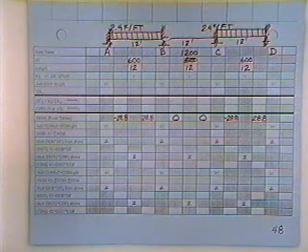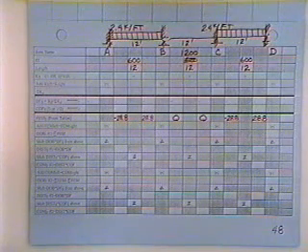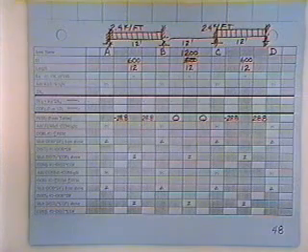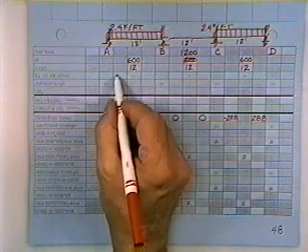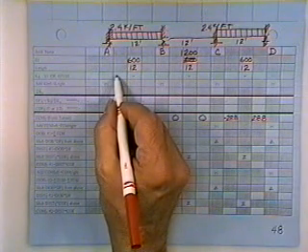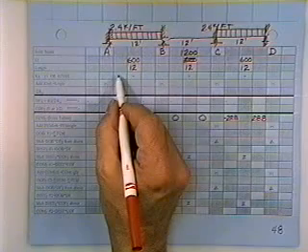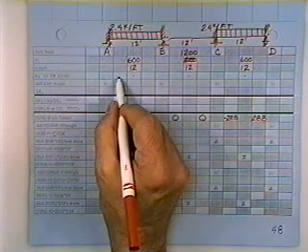If, on the other hand, you stand at that point on the beam and the other end is not pinned, I don't care if it's a member connected to it or a wall, it doesn't matter. If it's not pinned, then the K sub ij value is 4EI over L. So when you stand at A and look towards B, the other end is not pinned.